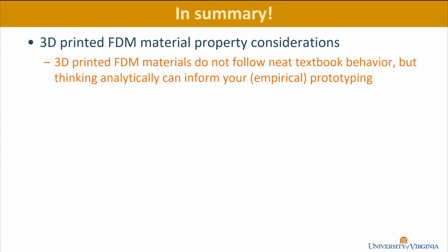But because 3D printed PLA and layered FDM in general is so different from the neat and clean textbook behavior, you really need to use some prototyping to help drive your design and not rely solely on textbook pencil and paper analysis.